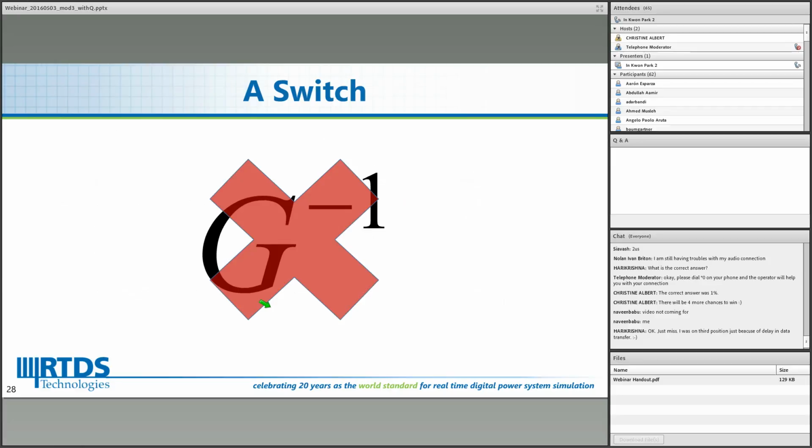So by carefully selecting that L value and C value in the switching technique, small L, small c switching, we can make the admittance of those circuit elements the same. That means we can fix the G matrix, and we can pre-invert that constant G matrix before the start of your real-time simulations.